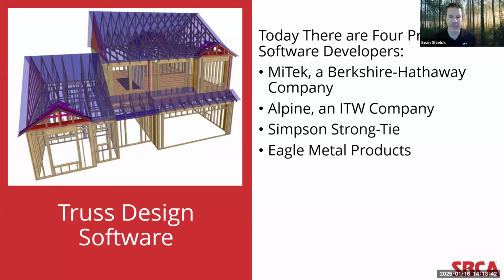Every component manufacturer in the United States uses one of these 4 proprietary design software suites to develop individual truss designs. And I bring this up and highlight it because, again, while truss design drawings are largely standardized, each software platform does organize the TDD output from their software a little bit differently. So if you're a building designer or building official who needs to review these things, that's one of the reasons why you'll see subtle differences from one set of truss design drawings to another.